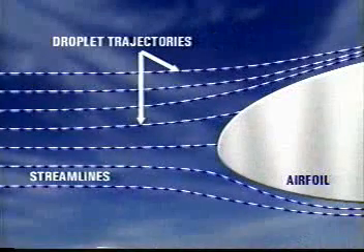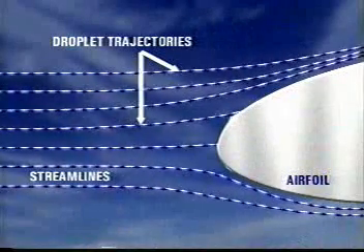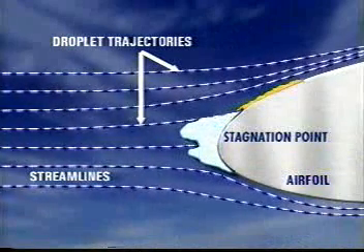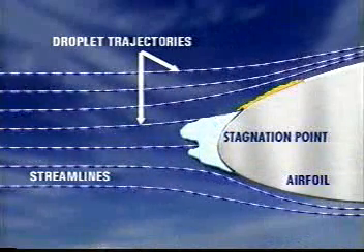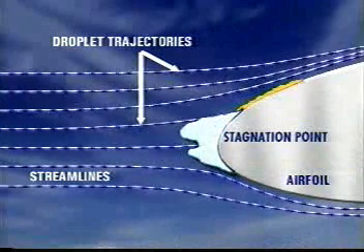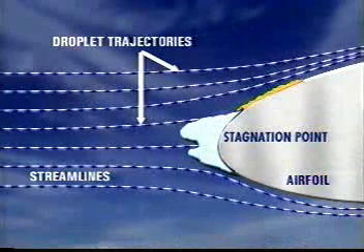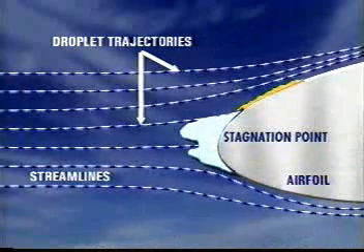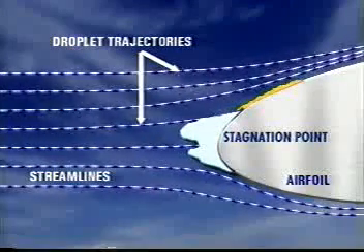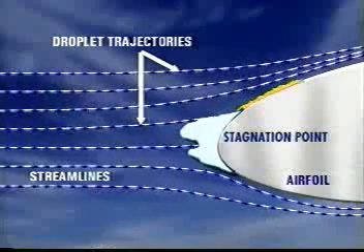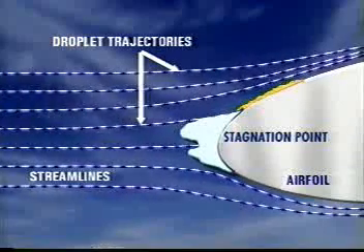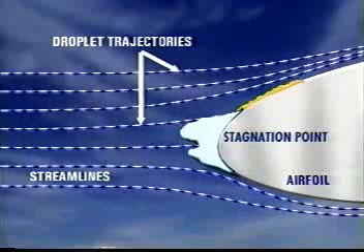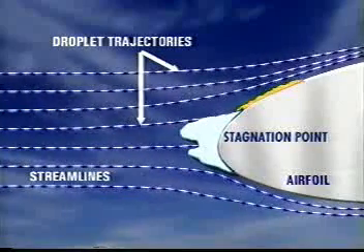In flight, ice will normally accrete in areas around the aerodynamic stagnation point. If ice droplets are big enough, they will strike the wing farther aft, creating a variety of shapes, thicknesses, and textures of ice, effectively changing its shape. Changing the shape of the airfoil will change the airfoil geometry to produce a new airfoil in which the lift, drag, and pitching moment characteristics are different from the wing's designed airfoil.